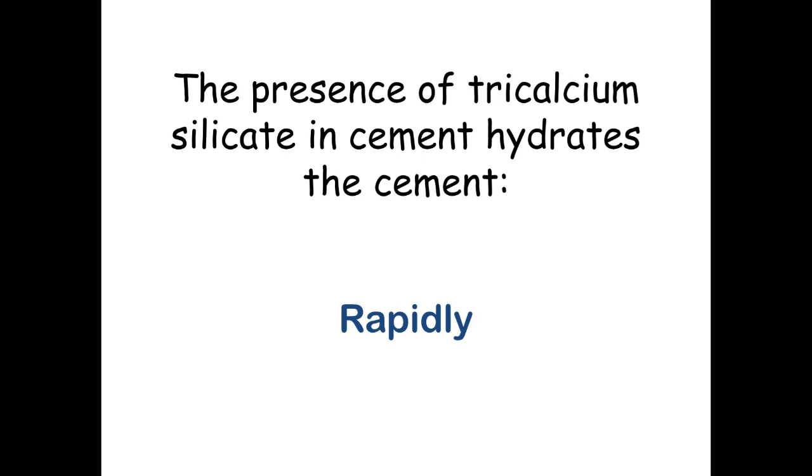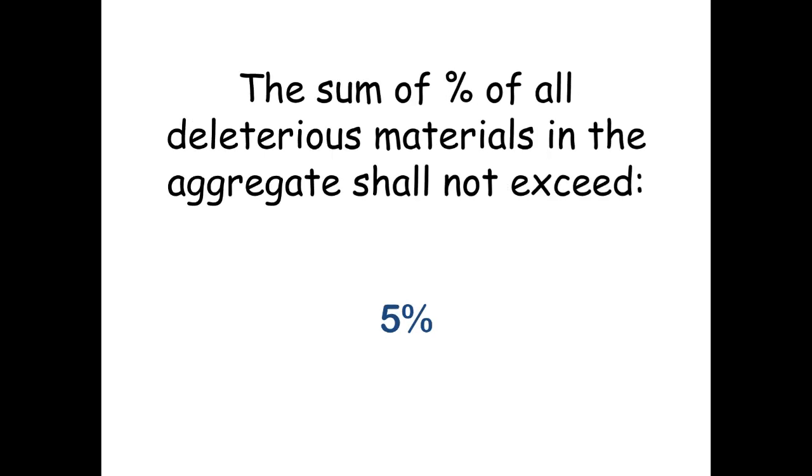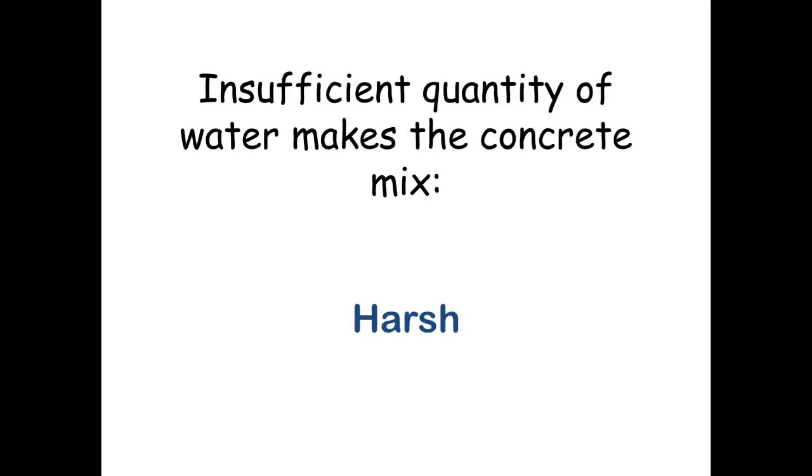The presence of tricalcium silicate in cement hydrates the cement rapidly. The sum of percentage of all deleterious materials in the aggregate shall not exceed 5%. Insufficient quantity of water makes this concrete mix harsh. Water content ratio is generally expressed in liters of water required per bag of cement. Water cement ratio.